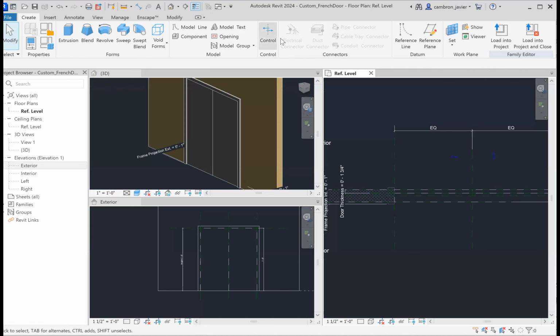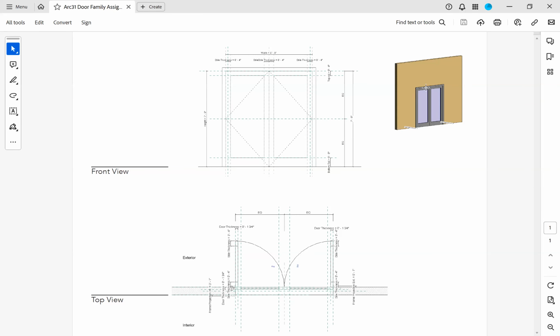Okay? And if we take a look at the door, we'll see that the door itself has a frame all around, and it has a thicker frame at the bottom. Okay. Now, just so that we understand the terminology, when talking about doors and the frames around the doors, the top portion right up here is known as the rail. So we have top rail and we have bottom rail. Okay. And typically, depending on the type of door, but most exterior doors, the top rail is actually thinner than the bottom rail.